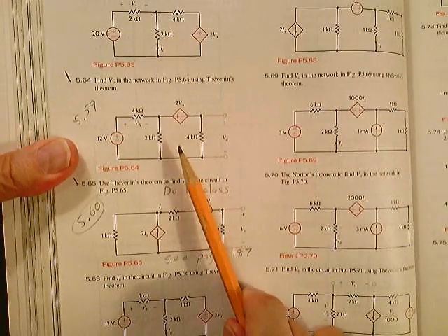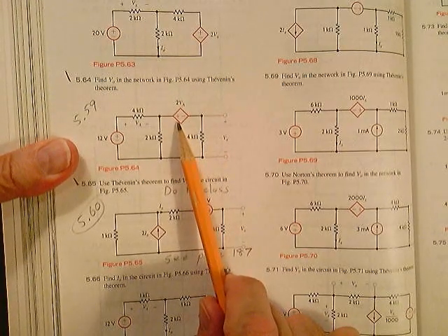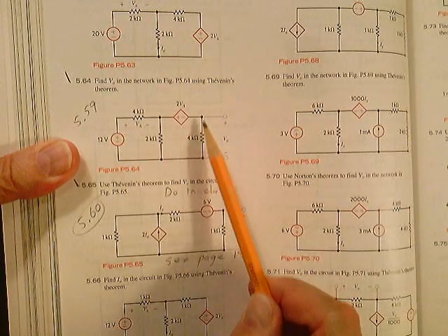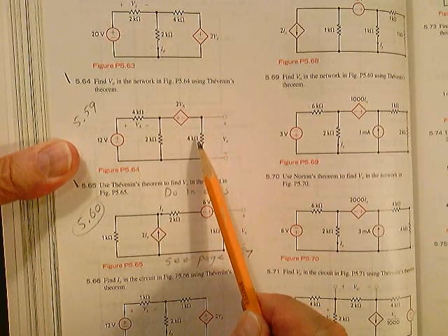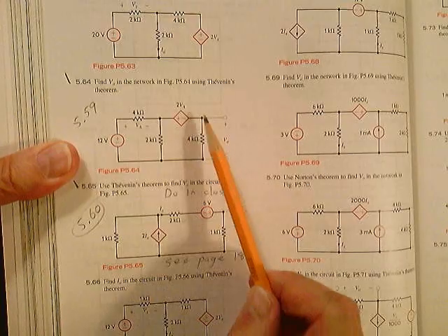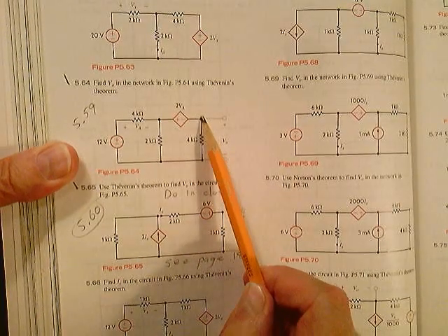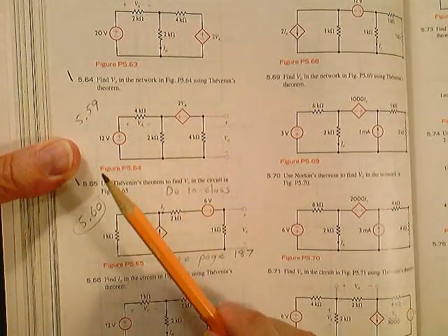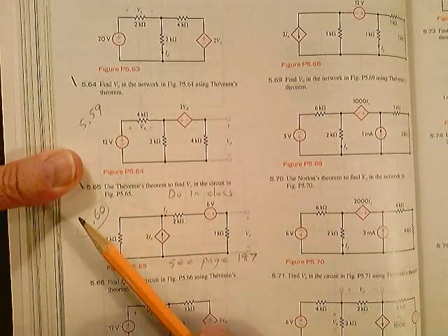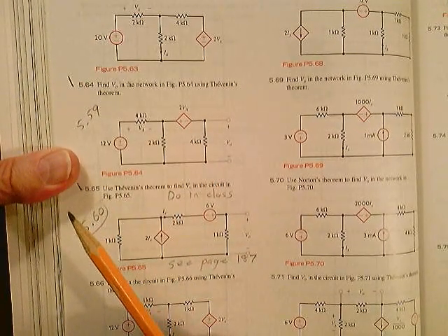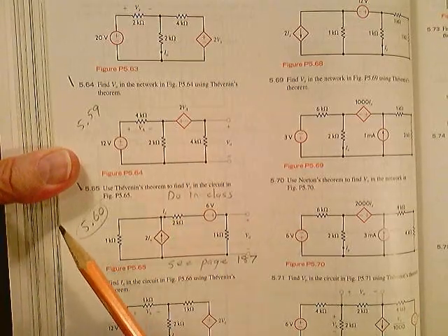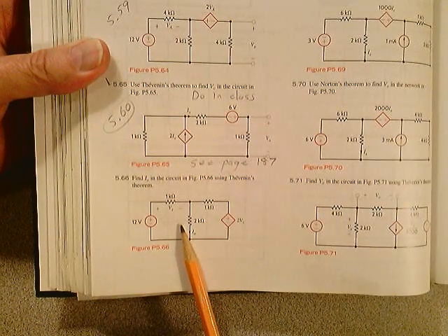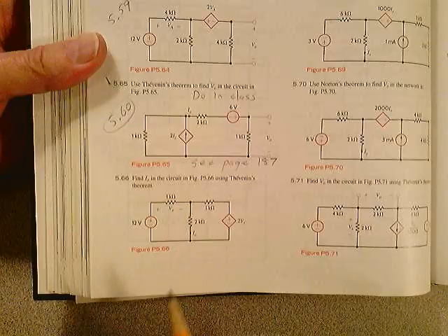Problem like this, same thing. Dependent source, and here's where they want you to find the output voltage across this resistor. You remove this resistor because that's where you're trying to find the voltage across. You make that the load resistor. You label this terminal A and this terminal B. You find the open circuit voltage. You find the short circuit current. I don't care if you use loop analysis, nodal analysis, superposition. I mean, we did a lot of these problems. I think it was in chapter 3 where we used loop and nodal analysis to find that. Same thing down here. Same thing down here. These are homework problems.